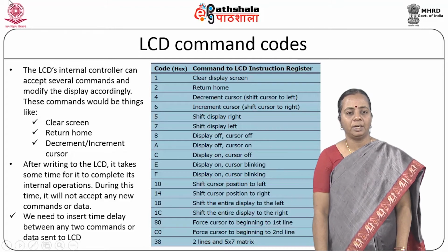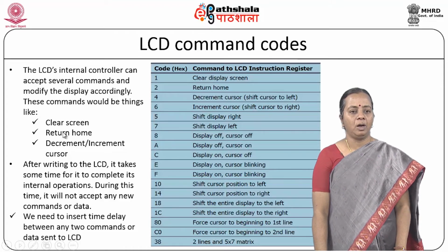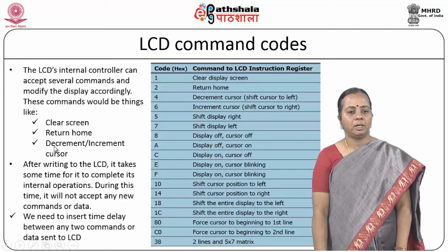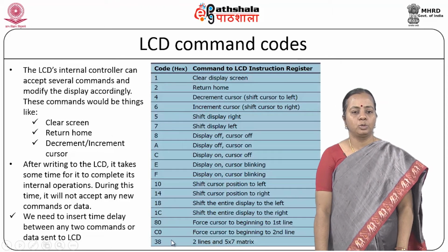When you are looking at a display, we always need to clear the screen. Sometimes we have to go to the top of the screen, sometimes the cursor has to be decremented or incremented from its position. All these things can be done by sending this kind of commands to the LCD.